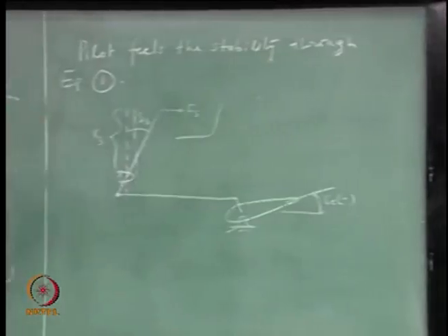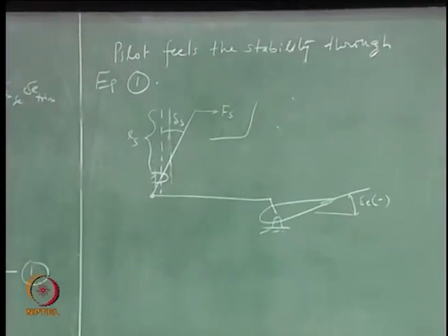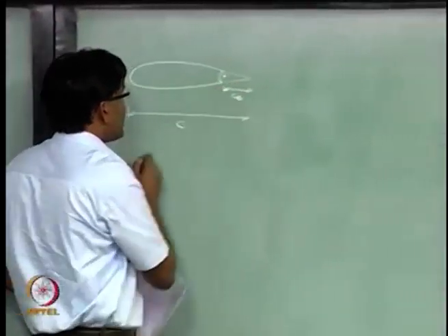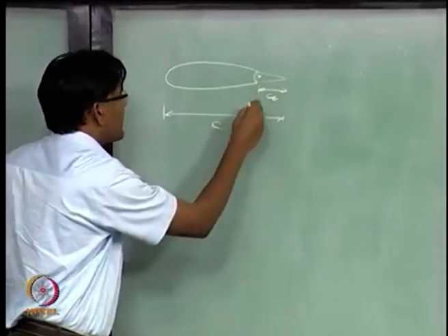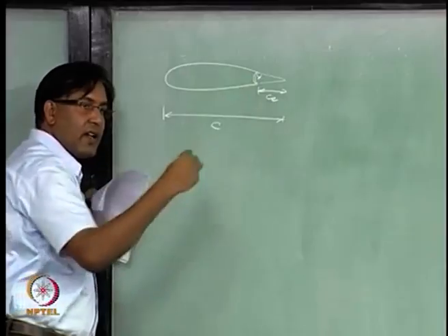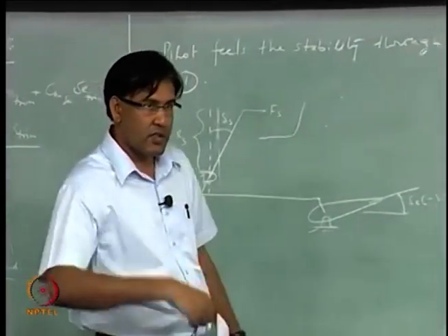Similar explanation we can give also for other control surfaces. So, hinge moment is the moment about this hinge line that the pilot has to overcome when he is applying the stick force.